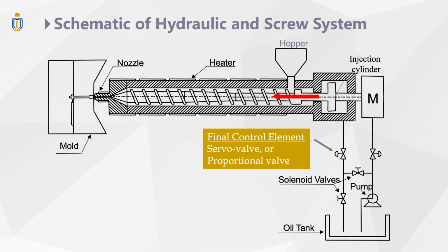So we started the work with an industrial request to provide feedback control for injection velocity. Injection velocity is basically the velocity at which you push the screw forward so that you can in turn push the polymer melt into the cavity. And before our work, actually, the injection velocity could not be closed loop controlled. It was done in so-called open loop control. So we took the challenge.